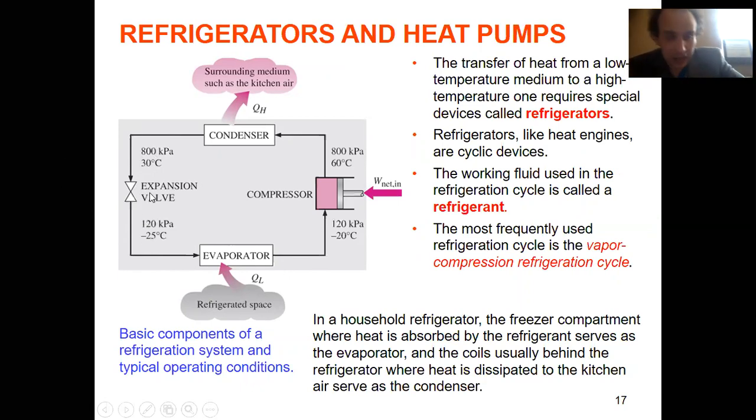We discussed it in chapter 5, right? And we discussed that if it was ideal gas, we would not see an expansion valve. That's why we use Freon, something really not ideal, that really has a throttling process here, right? That's why we can use Freon or water, but not ideal gas. If there was no expansion valve, the fridge would not work, right?